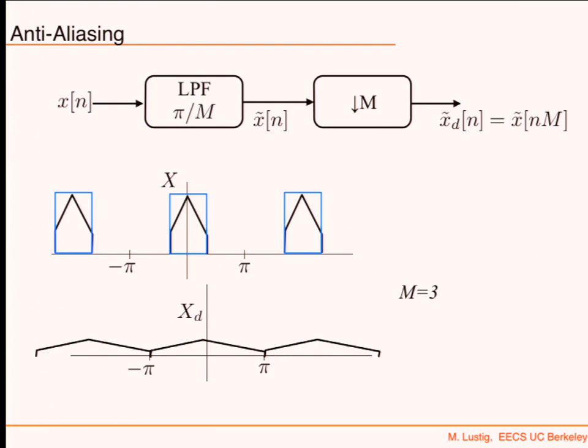Yes, there is a reason sometimes you get some aliasing, because we can never really get a perfect low-pass filter. So there is going to be some aliasing. Maybe you want to minimize it. And if there is some aliasing, maybe if we do a multi-channel or multi-rate type of analysis, we can then cancel it back. But obviously, it's not a desirable thing.